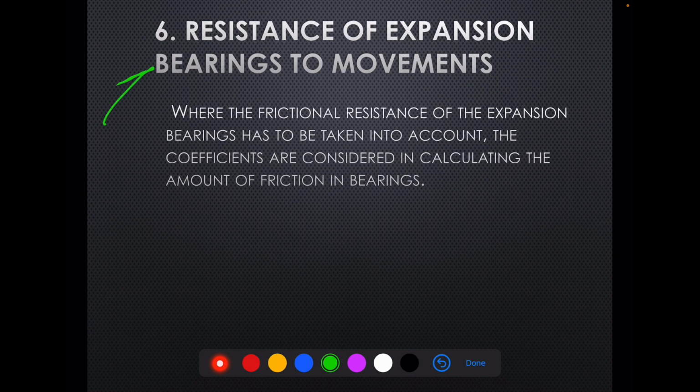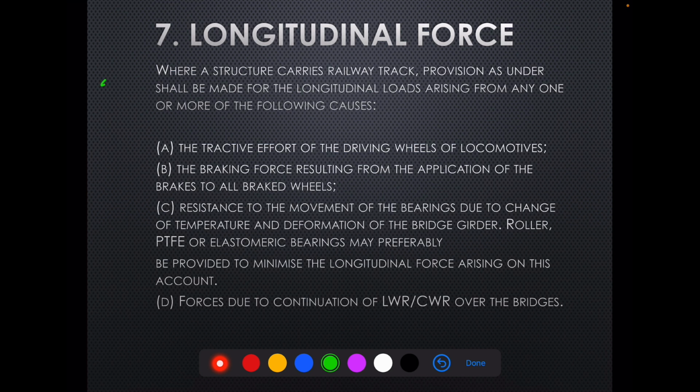Resistance of expansion bearings to movements, where the frictional resistance of the expansion bearings has to be taken into account. The coefficients are considered in calculating the amount of friction in bearings. Seventh, longitudinal force. Where a structure carries railway track, provisions as under shall be made for the longitudinal loads arising